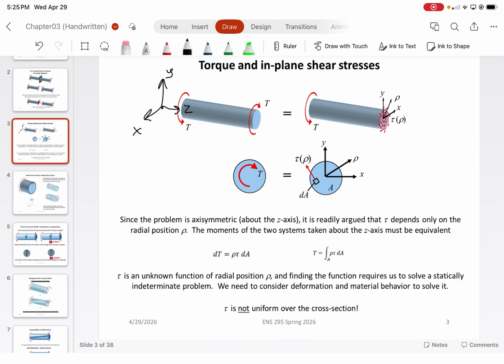Because again, shear stress is dependent on the area, and the shear stress will actually increase as you go further away. And we'll see why later on. But we can basically just state that the torque, the total force that's carried by the member, is just equal to the sum of all of the shear stresses times their areas times their radial position.